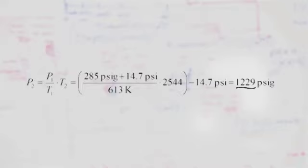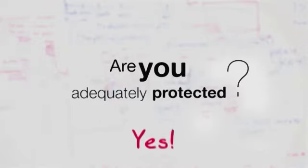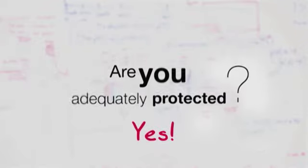That is well below the pressure rating of the vessel and the burst pressure of the relief device. So in this case, the potential for failure or release from complete combustion is not a credible scenario. So, are you adequately protected in this scenario? Yes, you are likely well protected.